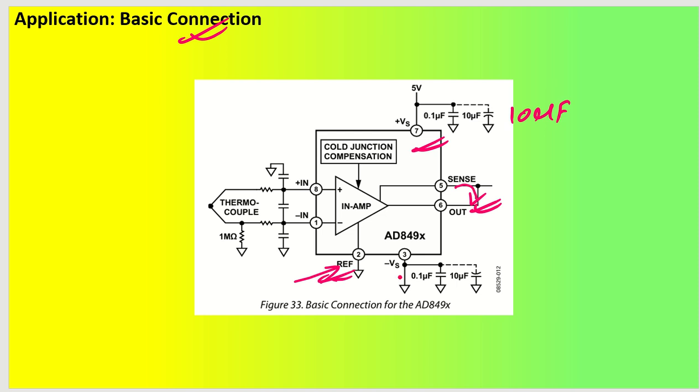Okay. Coming back to the input side, we have the thermocouple. So the thermocouple connection is here. Then we have two resistors in series for differential mode, let's say R1, R2. And then we have the common capacitors and differential capacitor, and this is how a complete filtering circuit is being designed, so that you can input your signal to the positive input and negative input of the IC. So this is the instrumentation amplifier inside, which is going to amplify your incoming signal by 122 times. Okay.